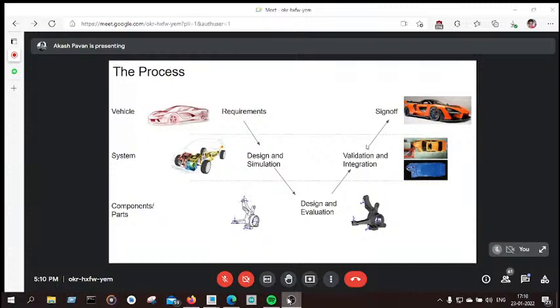And then we begin our prototyping. We begin the prototyping of vehicles. Once the validation begins, we get to prototype the vehicles. Initially a batch of 10 to 20 vehicles are built as a prototype, and those prototype vehicles are tested rigorously. While testing, we get to see a number of failures, and then those failures are captured, and then we get to change the design to rectify those failures. All those lessons learned will be taken, and that will be incorporated into the further design process.